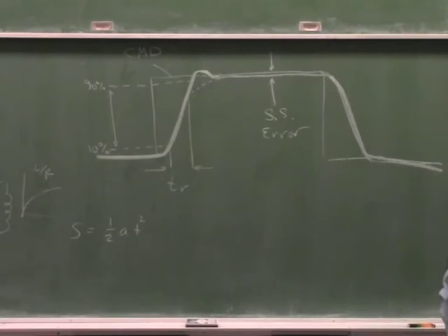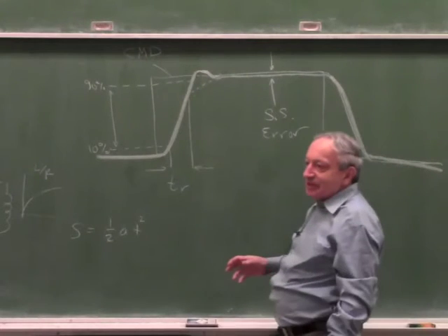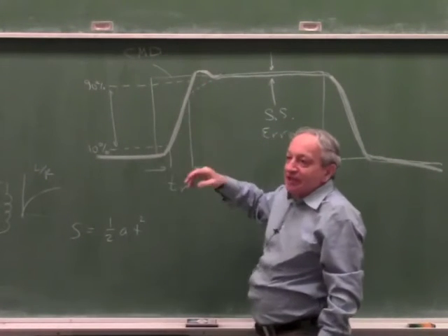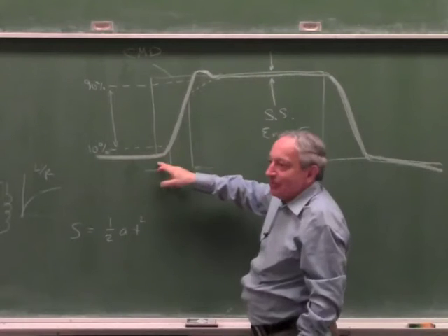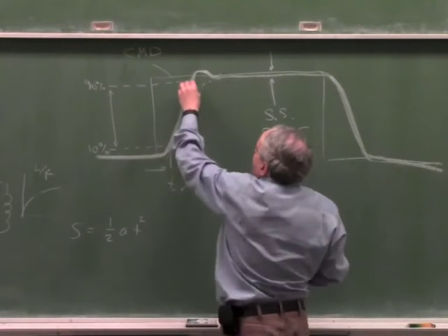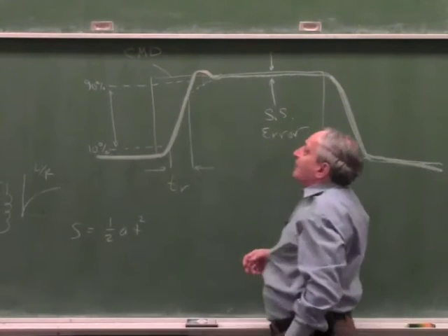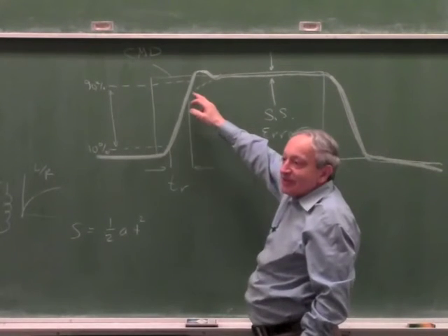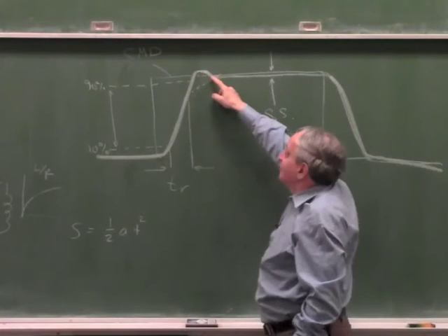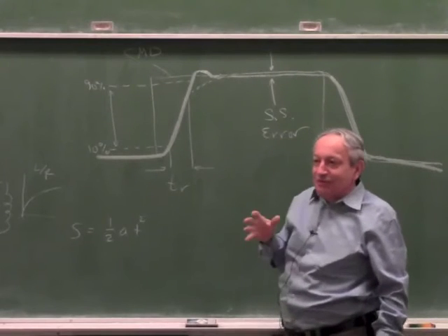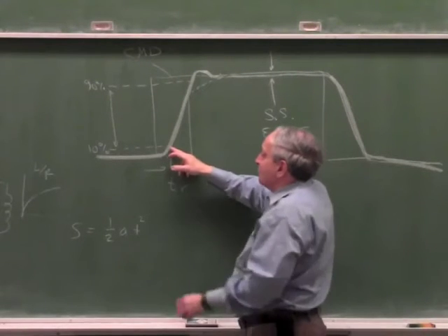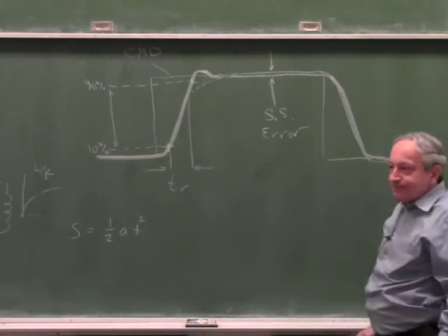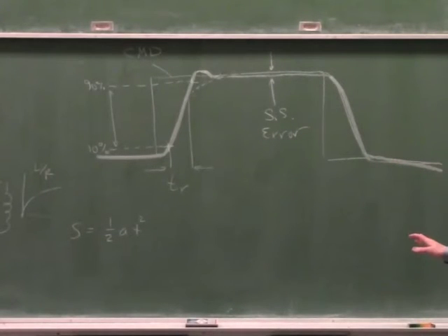Now, the reason why rise time is defined 10 to 90 and not 0 to full is because sometimes you don't see clearly what's happening here. If this is rounded and this is overshoot or undershoot, and you define rise time of the system by when it reaches 100%, some systems never reach 100%. Say they oscillate, so it's hard to define. It's easier at 10%, where it's already clear what's happening, and at 90% it's clear what's happening. Okay? So this is a typical servo response.